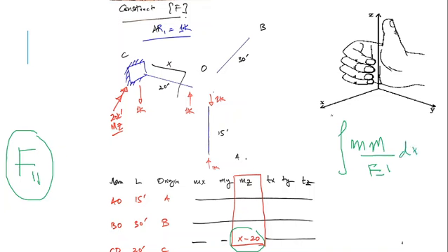It should be under the limit, because this is 20 feet, so there would be 20. It should be integrated under a limit because you are using the method of sectioning. You cannot use the conjugate beam method. Here x minus 20 has to be multiplied with itself within this limit.